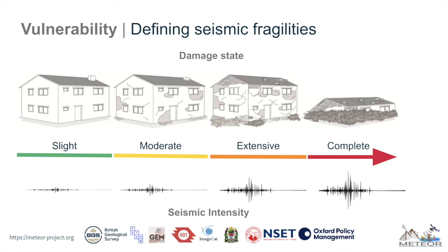However, we would expect that if a slight shaking of the ground occurs, it will produce visible damage, for example, in the form of cracks in the structure. The greater the shaking, the greater the damage observed. The intensity can be so great that it causes permanent damage to the structural elements, or even collapse the structure. Although this process is continuous and occurs in a particular way in each structure, risk modelers usually discretize it into defined states of damage. For example, low, moderate, extensive, incomplete damage or collapse.